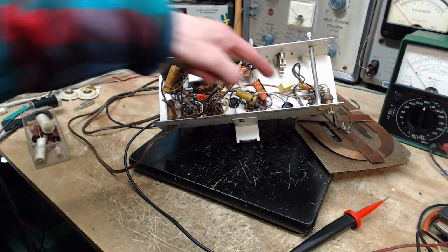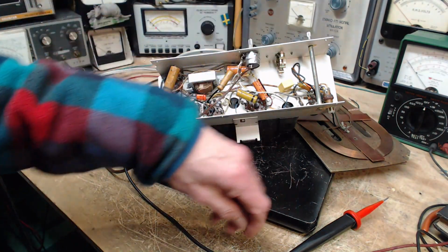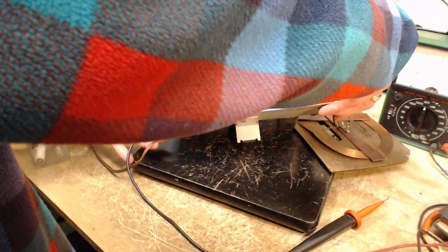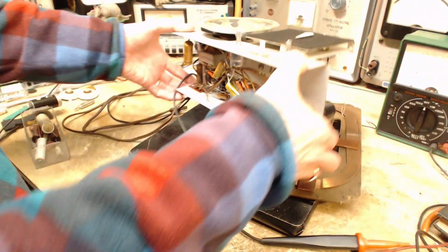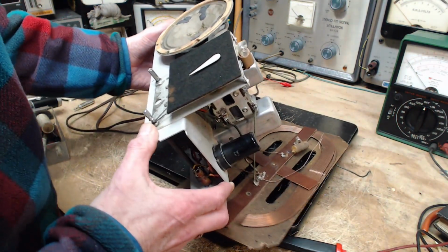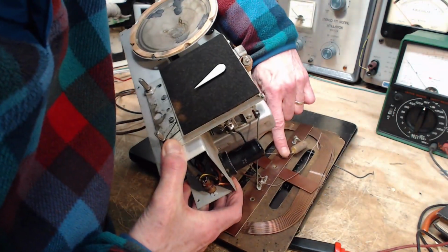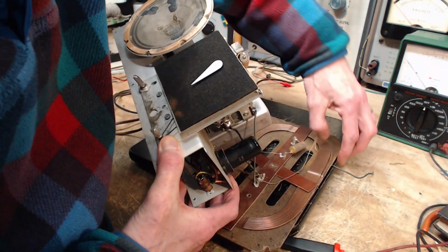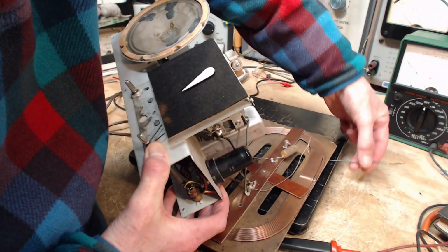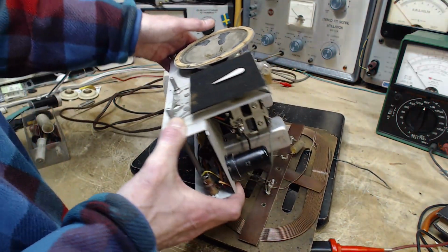We tie it back with a capacitor that will allow RF to whip through it, but won't allow AC current to flow through it easily. I'm looking at the antenna. See that capacitor on the antenna? So look, it goes from here to here. What's this? This is this green wire. What's this? This is the antenna wire. So if you want to extend a wire out, there's a capacitor sitting here protecting you and the radio